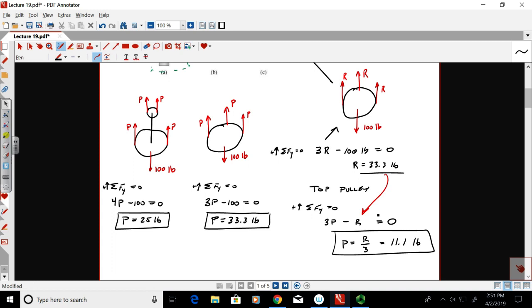So typically, even with pulleys, having a pulley system better than 9-to-1 is really hard to do. As you keep going with pulleys, you have so much friction, it tends to lock it up. So it can be difficult, right?